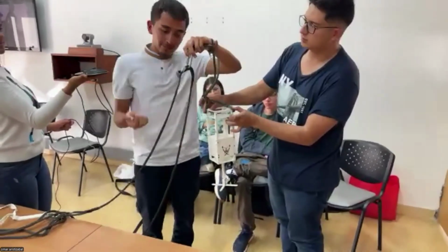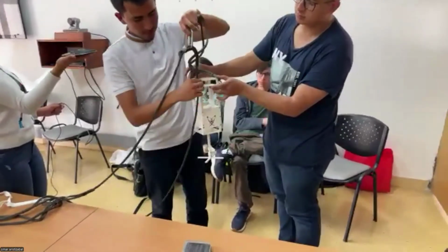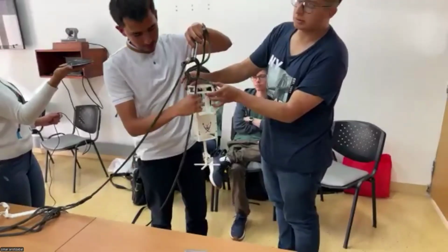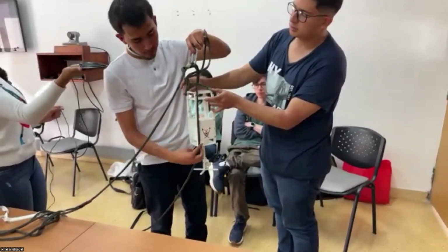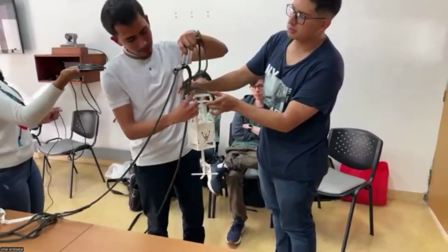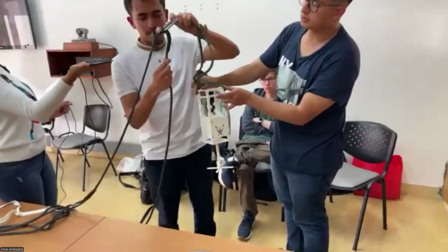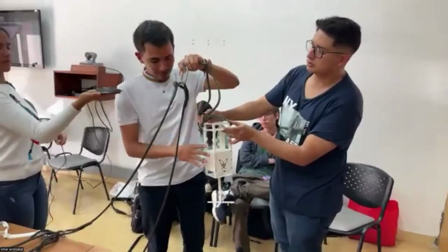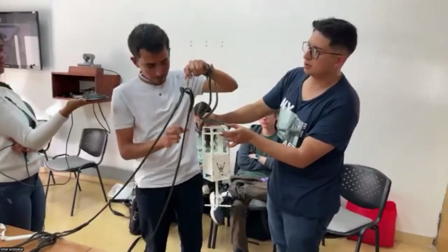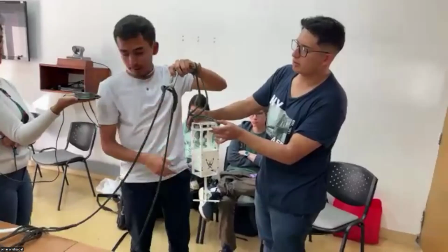But as an additional safety measure, the CubeSat has rail guides that allow this shock cord to be placed alongside it, so that there will be no relative movement of the CubeSat with respect to the shock cord, because we want it as still as possible. So that's in general how we attach the CubeSat during flight.